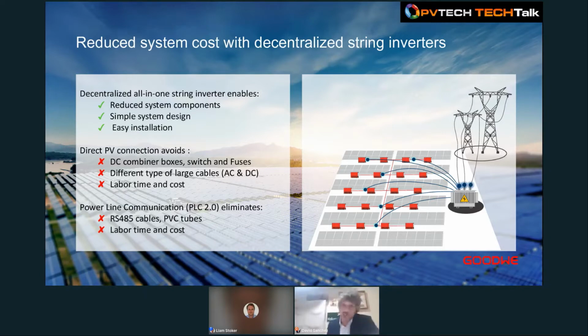When using string topology, string inverters, there is a clear saving in Capex, in BOS, right? As I mentioned, the strings connect directly to the inverter, and the inverter goes directly to the transformer. There is no AC box whatsoever. When comparing to a centralized solution, you still need to go through string boxes, etc. So instantly you have a big saving in BOS, due to components.